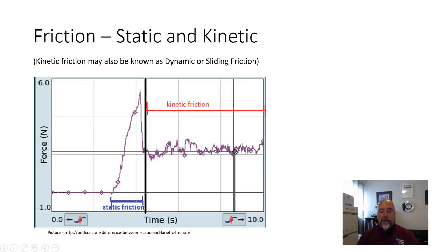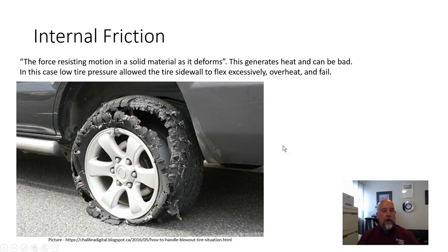If the tire is in contact with the road and the tread is gripping the ground, you can have a relatively high amount of traction. But as soon as the tire starts to spin or slide on the road, the amount of grip available drops dramatically. Okay, so you have this much traction if there's no sliding. You have this much traction if there is sliding, significantly less. Okay, internal friction, more friction.